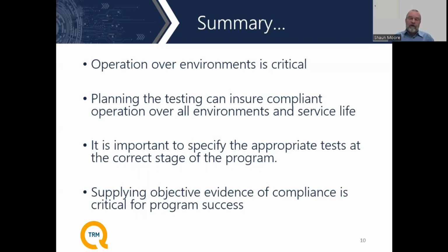Something else that's critical, especially for a lot of high-rel military space programs, is the objective evidence that the testing was done and how well it met the requirements. It's not always black and white, did it pass or did it fail, but supplying that objective evidence means everybody can look at the data to determine how well the part did at whatever stage of testing was being completed.